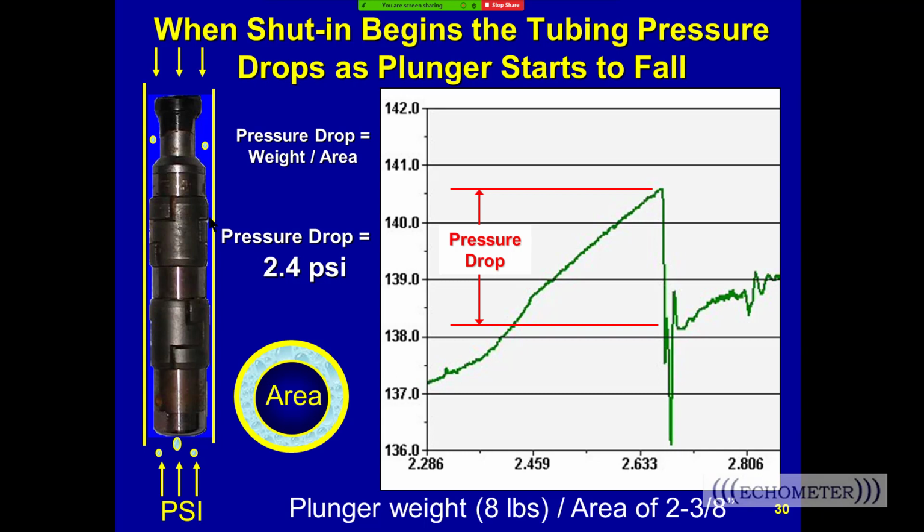But it'd be tough because you're going to have to make lots of cycles to make that liquid load small. The liquid load is what you're trying to lift, and you're trying to spread that liquid load out over many cycles, so the pressure's low. 15 barrels of liquid is like 1,500 psi pressure, and so you have to divide that 1,500 psi pressure by the number of cycles to get how much pressure per cycle.